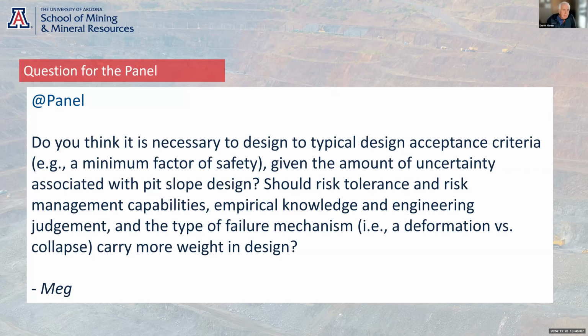So there's a lot of information that needs to be evaluated when you're looking at this whole business of the design acceptance criteria. Factor of safety is just one part of it, but it's the performance of how the pit walls have been developed, the mining rate, the deformation rates, how things settle down. Can you just mitigate it with a small buttress? All those things play into it, and I don't think the factor of safety is a governing thing, although we all like it because it's so simple. Doesn't mean it's right.